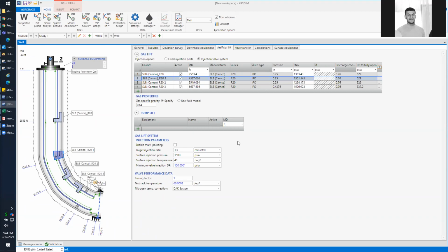So the thing is, when we model the multi-phase flow, if you can see the screen, when we inject gas lift here, the composition in this part of the fluid and in this part is not the same, because we injected the gas lift from this side. This will change the PVT properties of our fluid. So the question was: how can we model this change in PVT parameters due to the change of fluid composition? Let me show you.